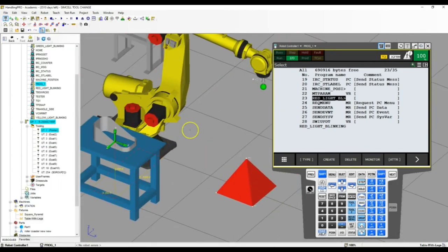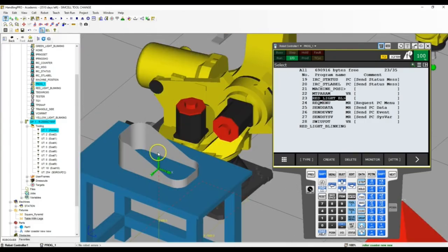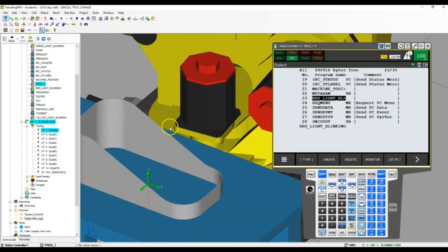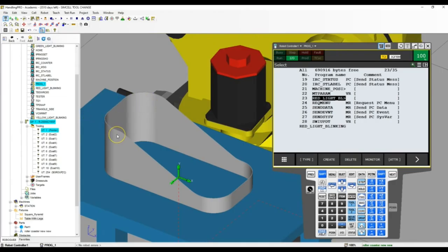So what we want to do now is run a path in which this pointer tip, our UTool, will match the entire surface of the top of this can here. So it has to go around, up this, and be perpendicular to it the entire time, and at the same speed the entire time. To program that by yourself is very, very difficult to do.